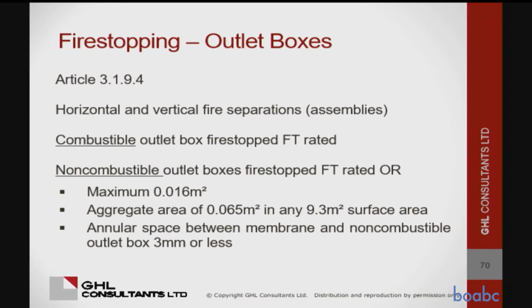So it's not super clear in that section. It says, and I'm going to try to say it here, it says the tightly fitted thing applies to vertical fire separations and membranes on assemblies or forming part of an assembly that's required to have a fire resistance rating. So it's like, well, does that word vertical only apply to fire separations? Or does it mean all of it?